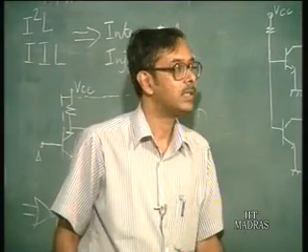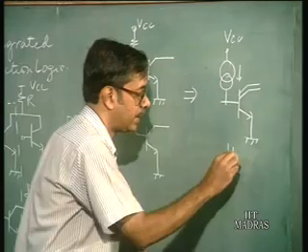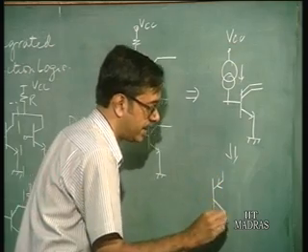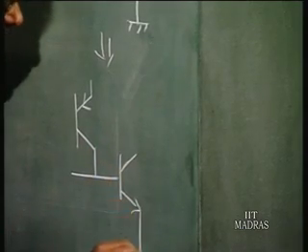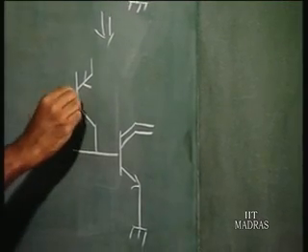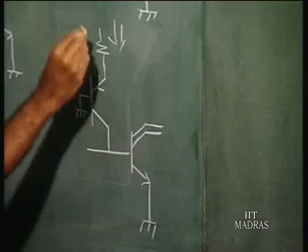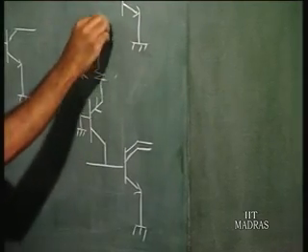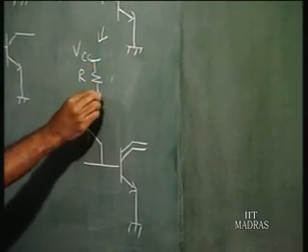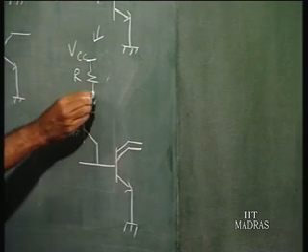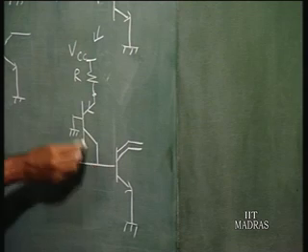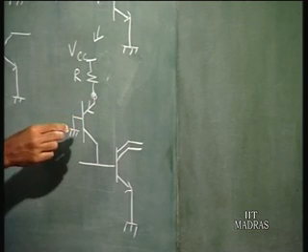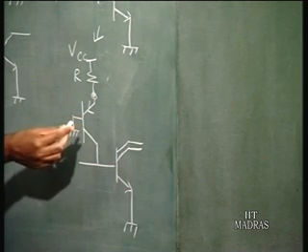Now, you can realize this current source. So, the next circuit which I will draw, I just replace this current source, I realize this current source using a PNP transistor. So, here it goes this way. You have a resistance here, a VCC and a resistance here. Now, this is the emitter, this is a PNP transistor, the base of this PNP transistor is grounded. Now, this emitter point is going to be more or less fixed at 0.7 volts.